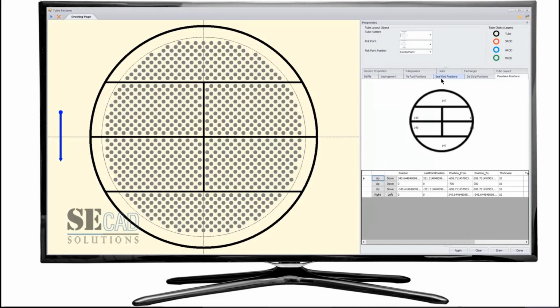By this way, you have a model on PVLite. You will export an Access database file from PVLite. After that, by using SEG software, you will read this exported MDB file and convert it to a 3D model on Autodesk Inventor. And likewise, you will create the 2D drawings of this equipment.